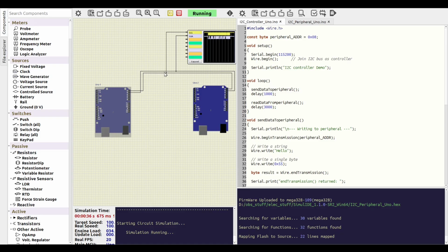All right, so it's definitely doing stuff. These are the watchdogs. We're not using those. RAM. So it's definitely moving data in and out around the RAM. Flash, it's not writing anything. It's just reading the program. We're not doing anything with the EEPROM. I couldn't tell you each of these status things up here. Maybe I'll make a future video. All right. Well, let's look at the other one.